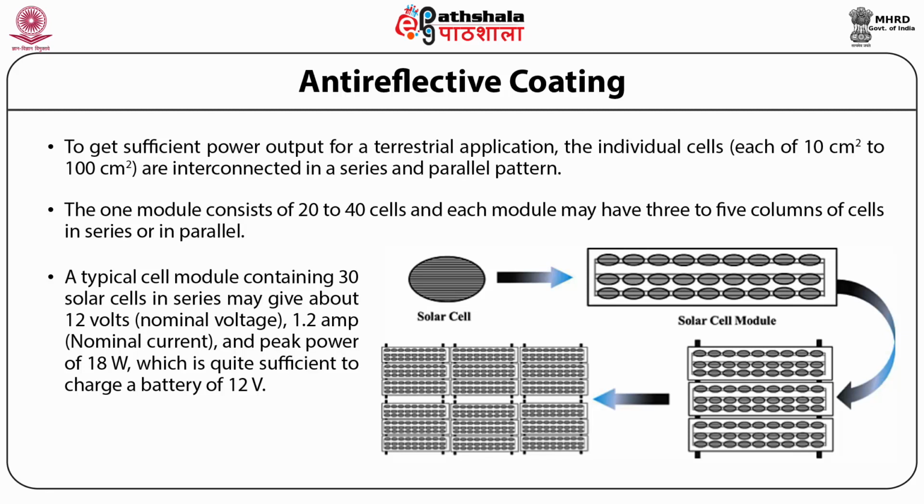The material used for encapsulation must have a life of more than 20 years, and it should be UV stabilized, should not increase the temperature of the cell, should have resistance to abrasion, and should withstand the temperature in extreme conditions and thermal shocks. The top cover should have high transparency for solar radiations, should be easily cleanable, and of course, it should be low in cost.